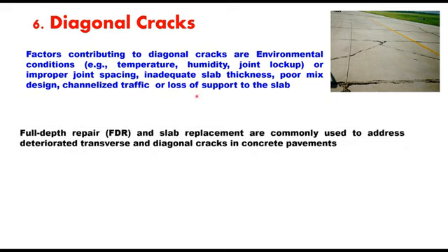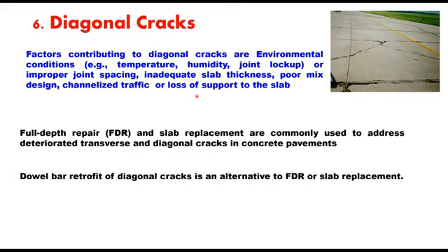Full depth repair and slab replacement are commonly used to address deteriorated transverse and diagonal cracks in concrete pavements. Double bars retrofit of diagonal cracks is an alternative to full depth repair or slab replacement. In this process, double bars are installed in slots across the crack, and it helps in providing good load transfer across the crack and reducing deflections, pumping, and further crack propagation.